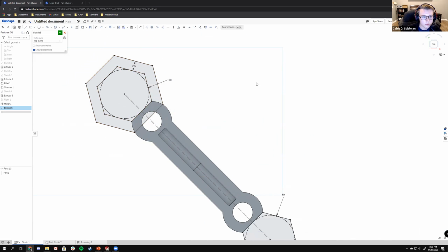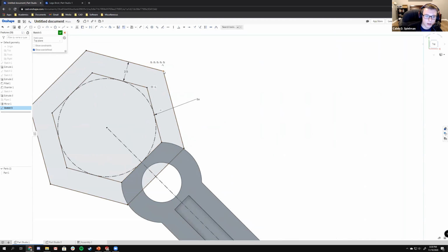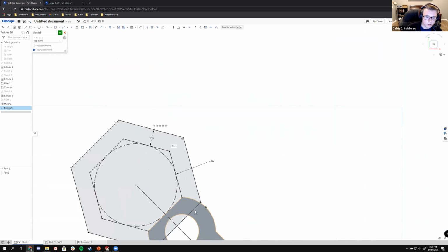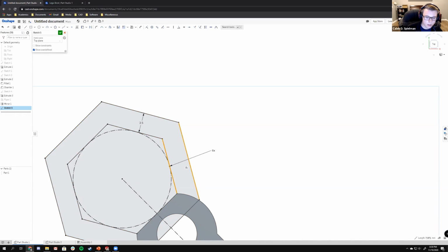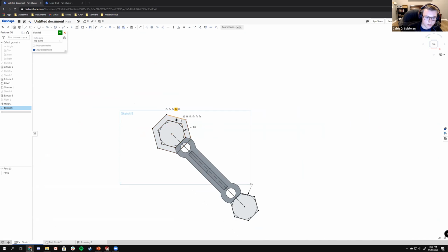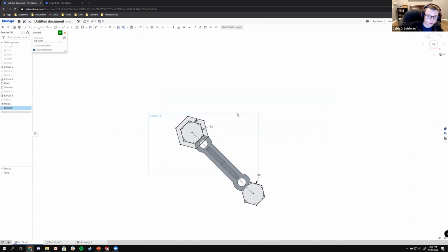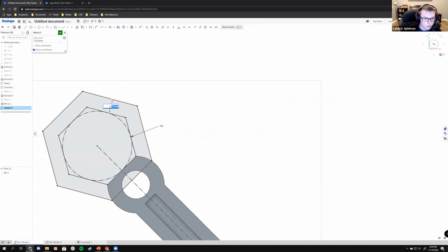2.5 millimeters. Okay. So what just happened is I defined an offset of these sketch entities. Essentially, this point, this line, and this line are the same distance apart from each other as this line and this line. That's just what the offset tool does. That's all. But I want to flip directions. So I'll do it again. Oh, this is so fun.